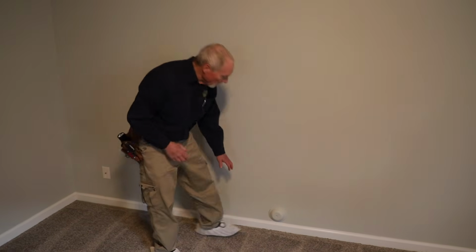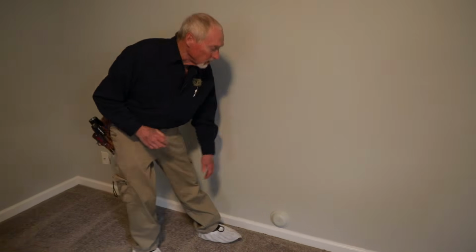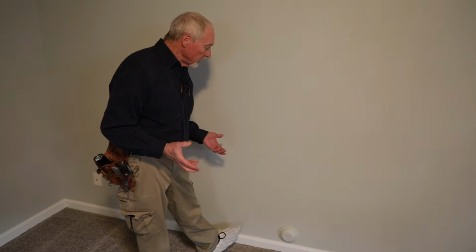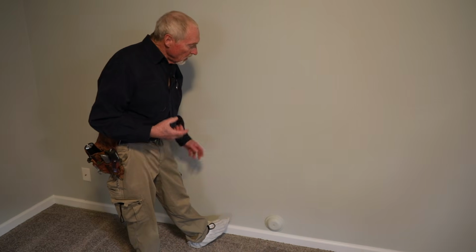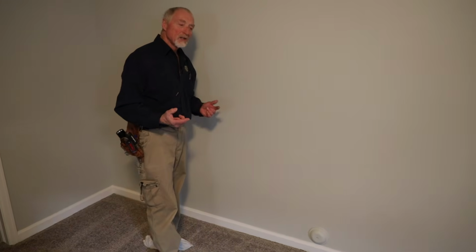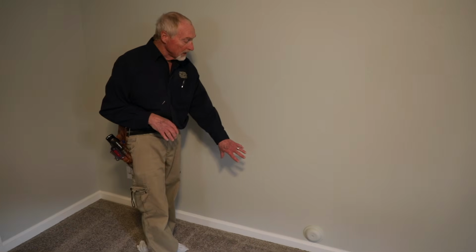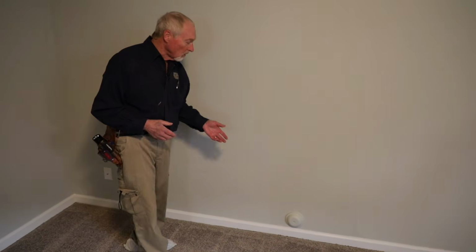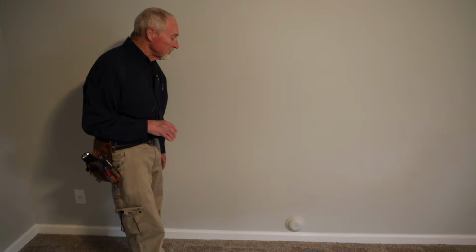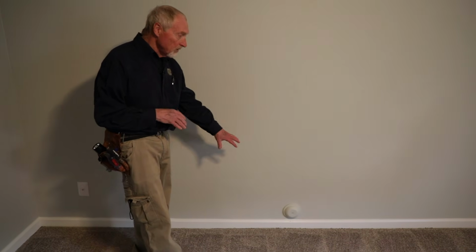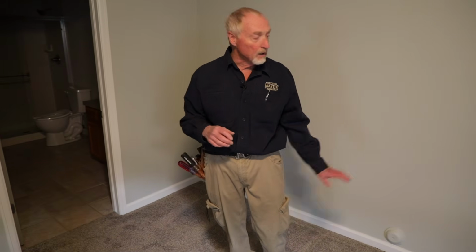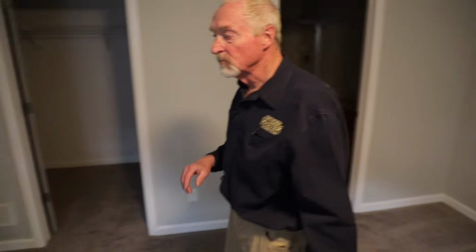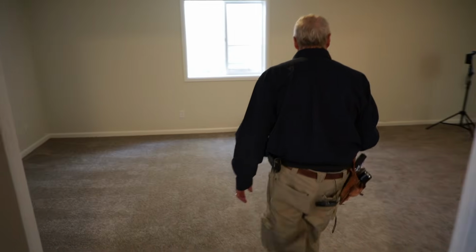So while we're here in the basement, we have this little cover here. This is, again, almost certainly over a clean out access point into the DWV drainage waste vent system. Clean outs must be accessible, and so this is what we like to see. It's better than just having a hole in the wall. Again, no requirement to take that off, take a look in there. Just you understand that that's what that is, a cover for the clean out access. And we have probably some more around in the basement as we go around, but just letting you know that's what that is. So, well, this one's got a different type cover on it.